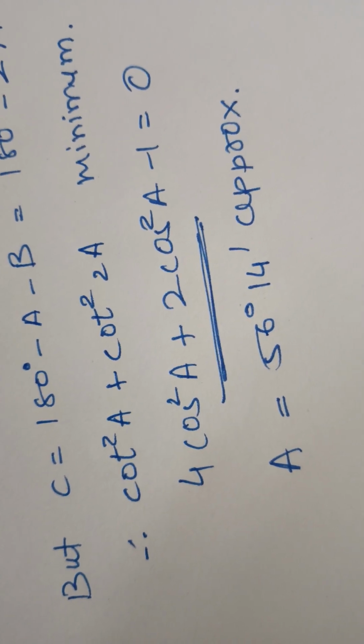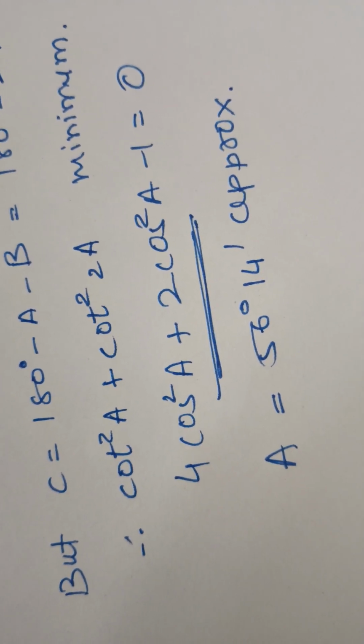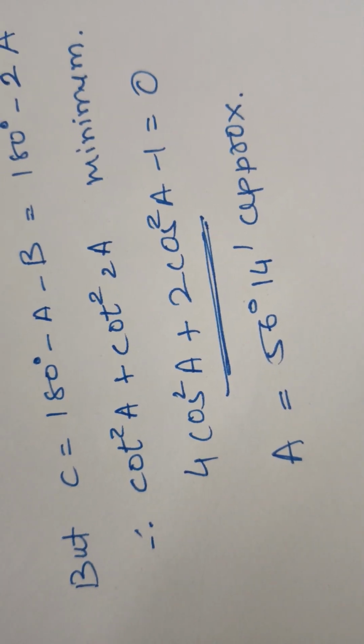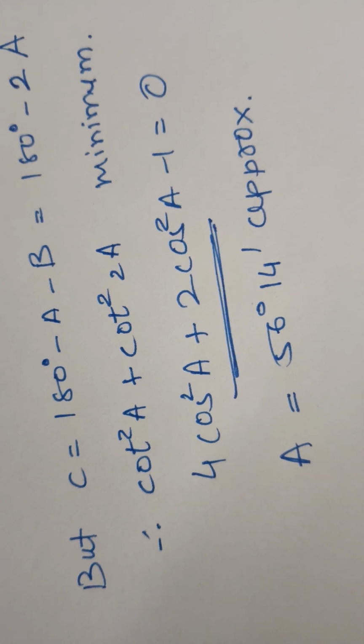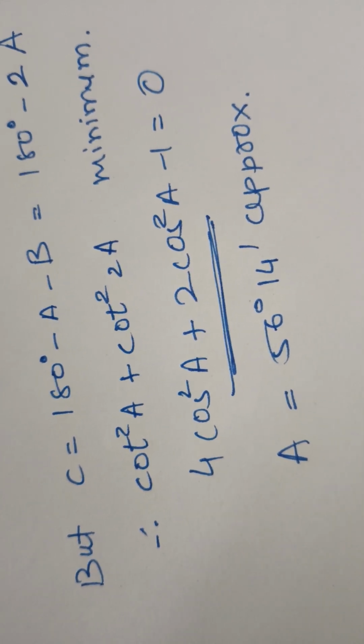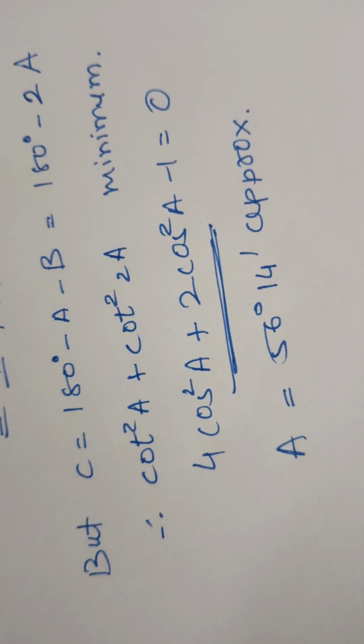However, from practical considerations, an equilateral triangle is the most suitable. So we have to always remember that angles smaller than 30 degrees or greater than 120 degrees should be avoided. Thank you.